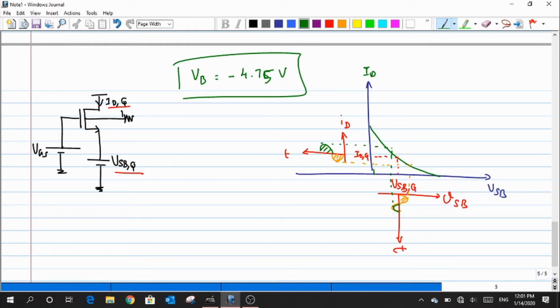No. The point is that I am fixing the value of VGS and VDS to a constant value, and that is the assumption that we have to use. Yeah, the AC current is flowing because of the change in the value of VSB. I'm trying to have a wiggle, meaning I'm trying to add a small signal around this particular Q point, but I'm not adding anything here. This is not creating the small ID. This is fixed to a value ID.